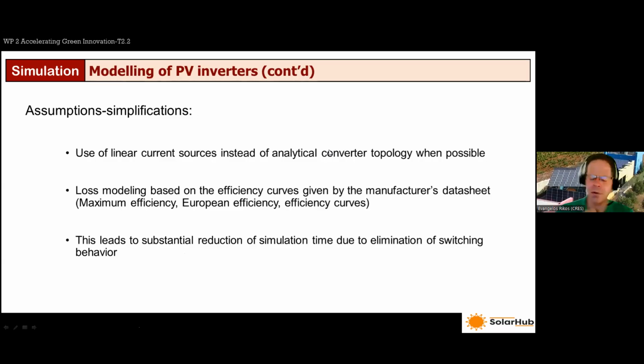I'm not entirely sure, however, that this is a problem per se, because we mentioned here that the DC voltage could be up to 700 volts, but on the other hand, if a household is equipped with a three-phase power supply at 400 volts, this means 3 times the power of one phase, right? So this is also the scope of having three-phase systems, among other things.